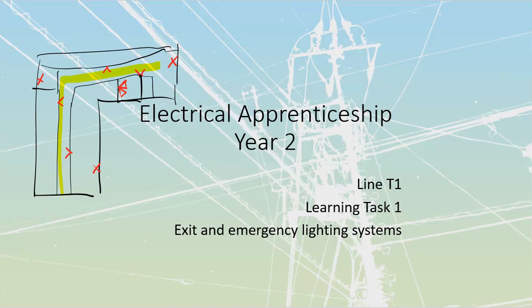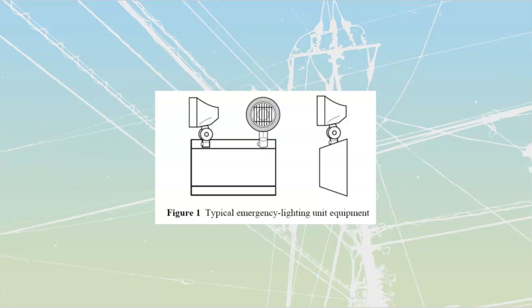And we're going to have some sort of bulbs inside of them, for exit lights and for our emergency lights. Usually they're going to be plugged into systems. They're not always plugged in. At times they can be wired in, but it's very common to see that they go to a little receptacle up top over there, and then you just plug them in. You're going to have a receptacle mounted up high on the wall, 2.5 meters minimum, that is going to plug into these things. As soon as power is lost to that receptacle, this emergency light would automatically kick back on.